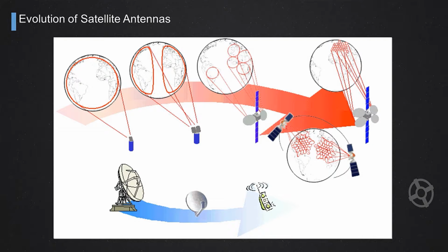To get a higher gain, we know now the trick. The antennas are not producing energy, they are just concentrating energy. So if I want to get a higher gain, I have to reduce the illuminated area. So if I get 20 dB gain with a global coverage antenna, and I want to increase it, what I can think of is to divide the global coverage into 2.